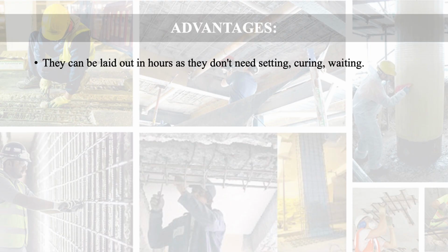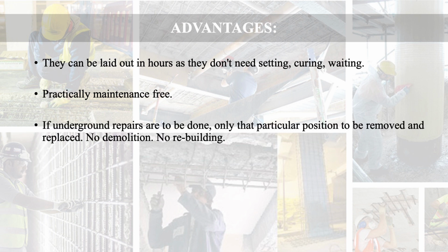What are the advantages? They can be laid out in a few hours as they don't need setting, curing and waiting. Practically these are maintenance free. If underground repairs are to be done, only that particular position is to be removed and replaced. You can easily remove these pavers from that particular position and again you can easily replace them. This does not involve any demolition or rebuilding. That way it is very easy.